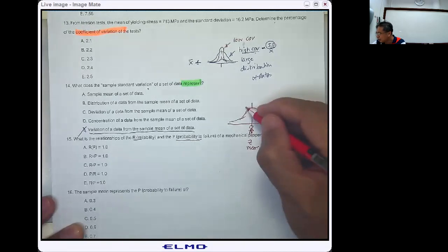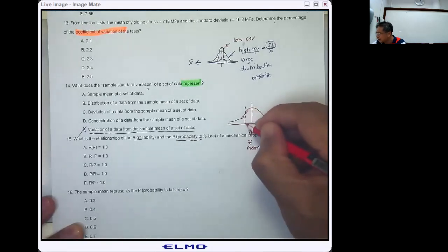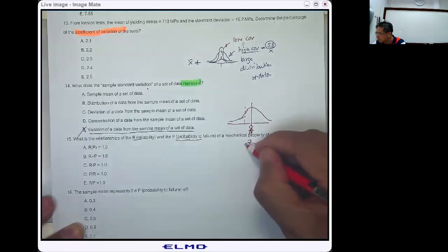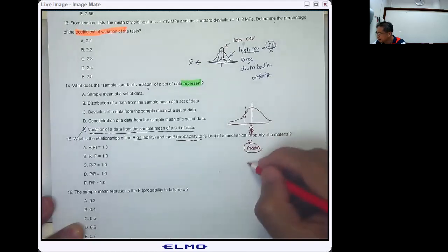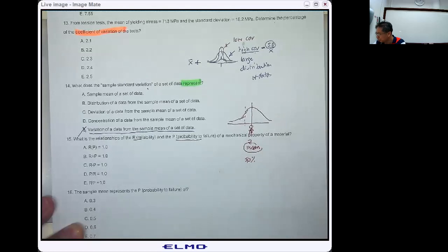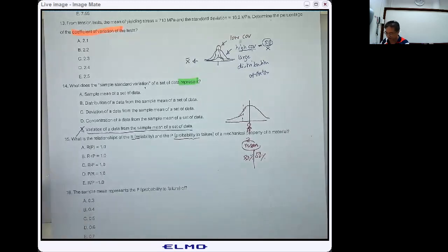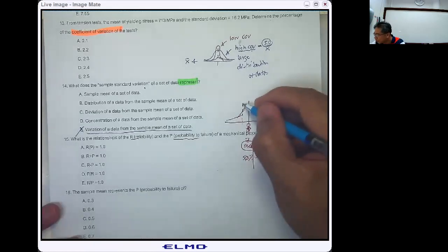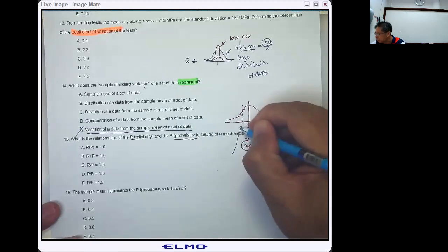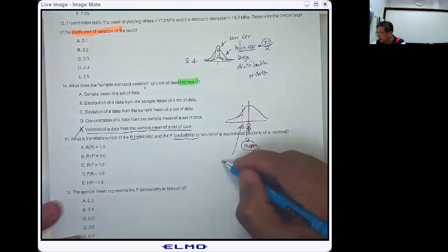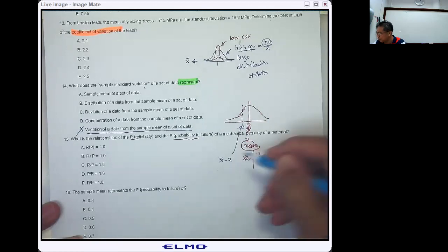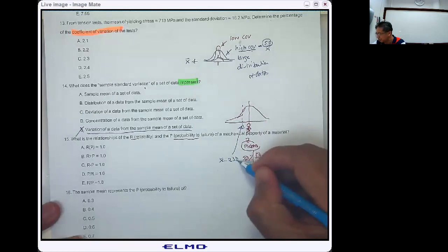And then when we talk about the statistical analysis, when we use the mean of the data, it means 50% is going to fail, and another 50% is going to pass. And to make your mechanical property more reliable, most of the time we must subtract from the mean some specific multiple of the standard deviation.